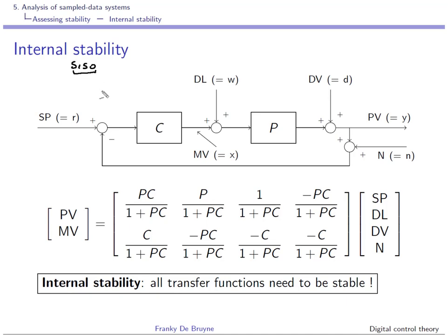I will show you again how you can find these transfer functions, and I will do it directly in the multivariable case so that these quantities will become transfer matrices, and you will see that you will have a different result than what you see over here. So this is only valid in this SISO case.